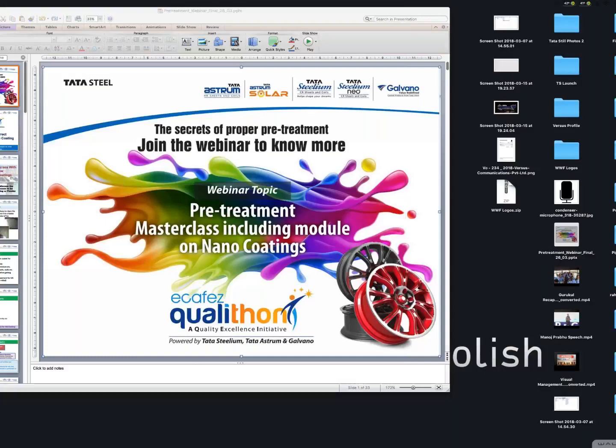If you store it for more than 4 hours, micro corrosion will start inside the coating, which may not be seen by bare eyes, and after that if you coat on top of that, probably you will have an issue, so better don't do that.